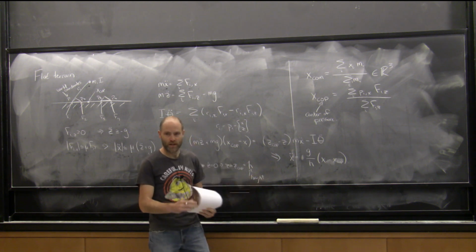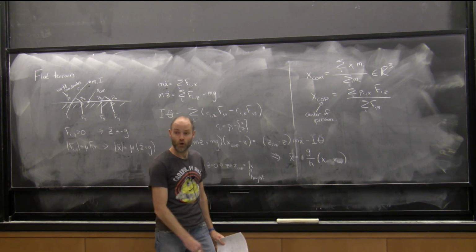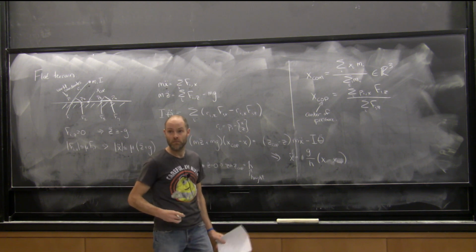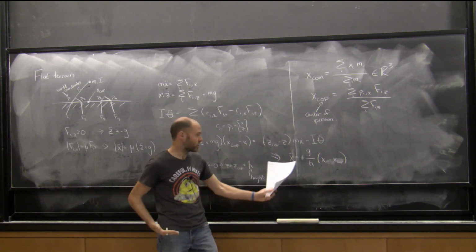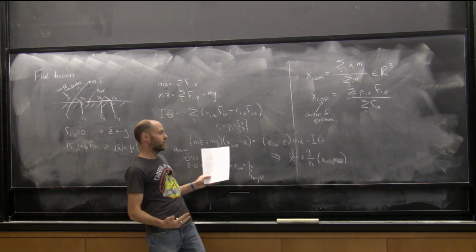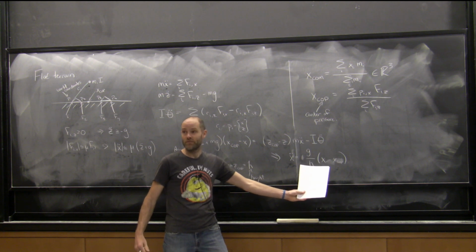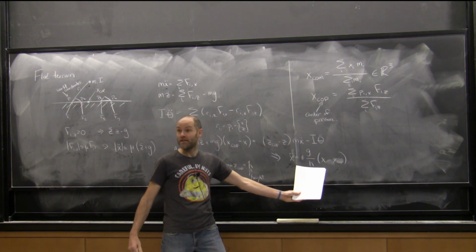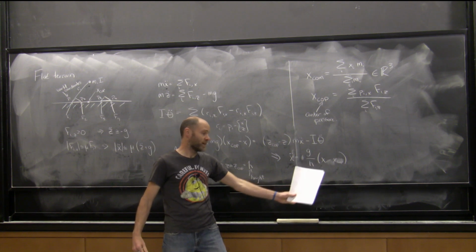Similarly, I can go the other way, right? If I want to control my center of mass, I can move my center of pressure. If I want to control my center of pressure, I can move my center of mass. They're just linked up like that. They have to be in step. And the relationship is never very complicated, but it's particularly simple: a linear equation, a linear dynamical system. This is a non-minimum phase linear dynamical system, for those of you that think about linear systems a lot.